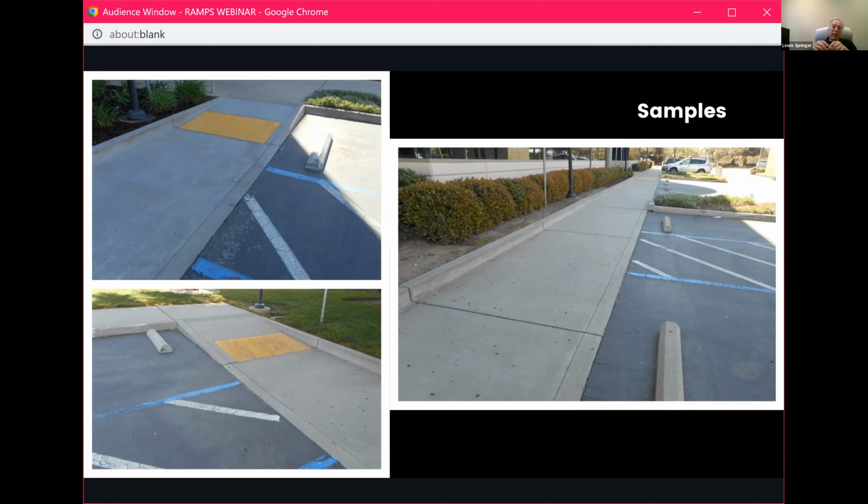So in this design, as you come down the curb ramp, it's actually telling you you're entering a vehicular area. And as you travel across this accessible route, which is the wrong intention of that detectable warning. So here it would either be put the detectable warning along that entire strip, separating the vehicular area from the walkway.